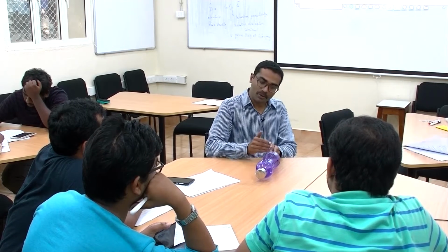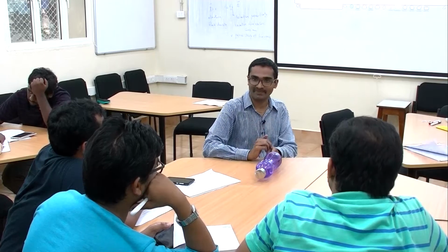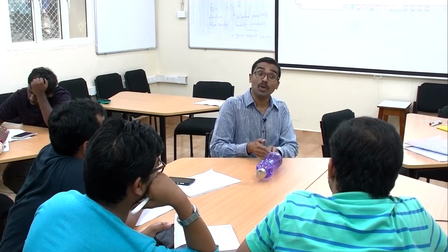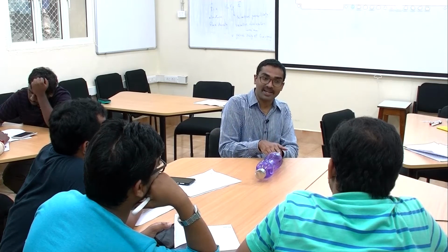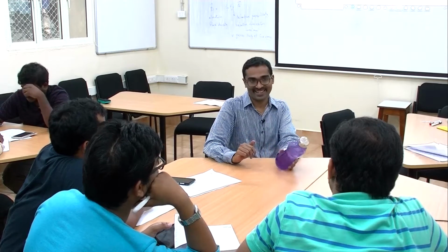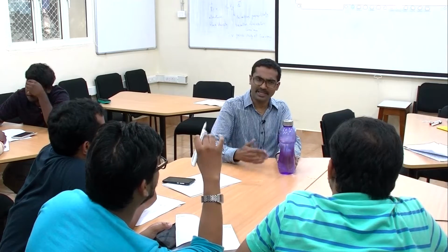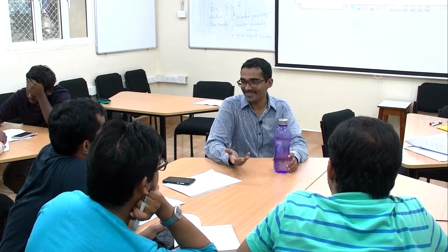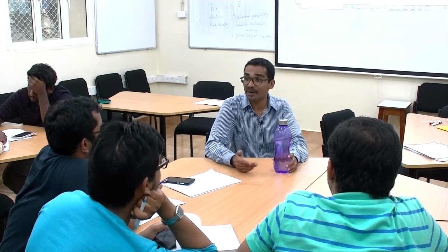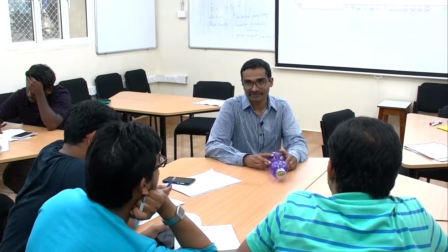On the other hand, if epsilon double prime divided by epsilon prime is very, very small, much smaller than 1, that means there won't be much loss here, so it will propagate. If it is perfectly zero, no loss occurs anywhere. It will just go through. Whatever you are sending in here will come out here. Does that loss depend upon frequency? Of course. So epsilon double prime divided by epsilon prime is highly frequency dependent.